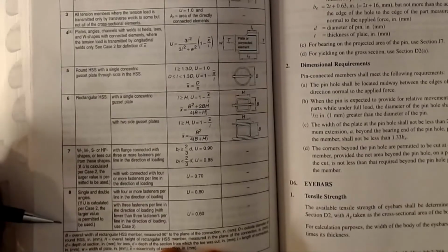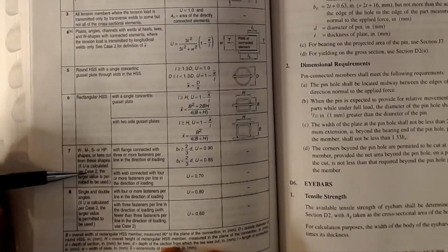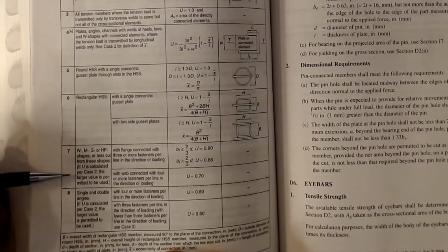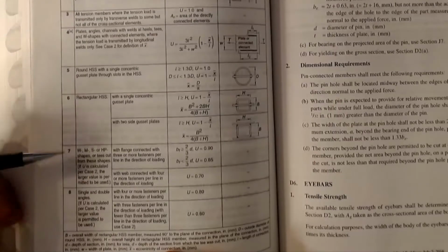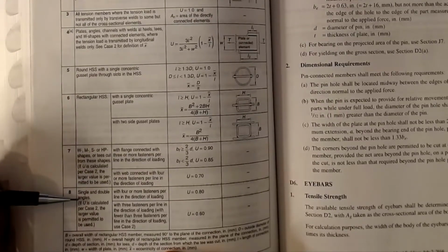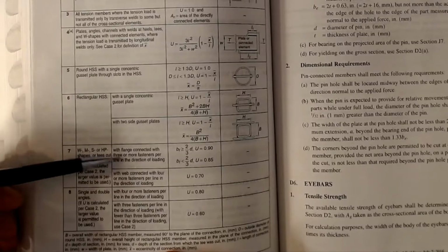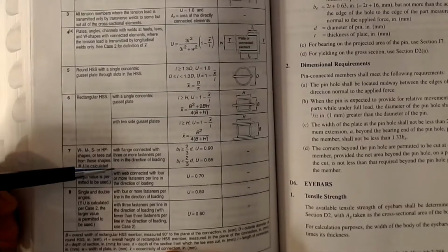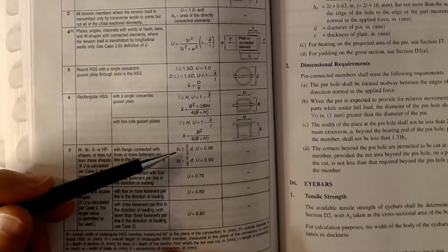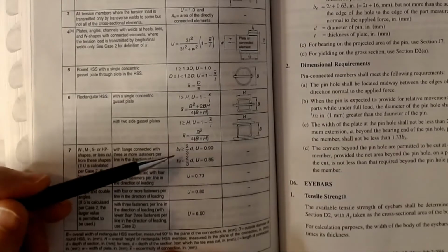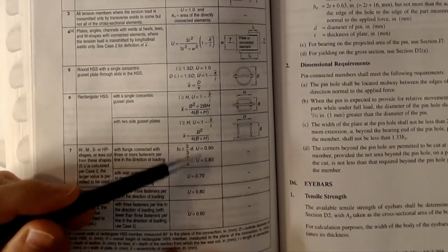The last two pertain to the rest of the rolled shapes, case 7 and case 8. Case 7 is W, M, S, or HP shapes, or T's cut from these shapes. You'll notice at the very end there is an extra statement that says if U is calculated per case 2, then you are allowed to use the larger of the two values. The cases down here in 7 are with flanges connected with 3 or more fasteners per line, meaning I have 3 bolts in a line down the length of the member, not in a cross section. I can calculate U based on a comparison of the flange width to 2/3 of the depth, and for flanges being connected, I can go from 0.9 down to 0.85.